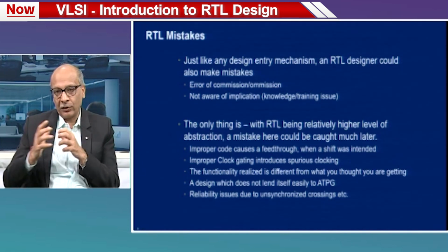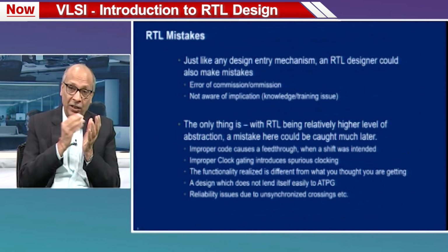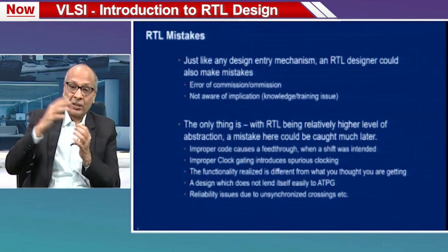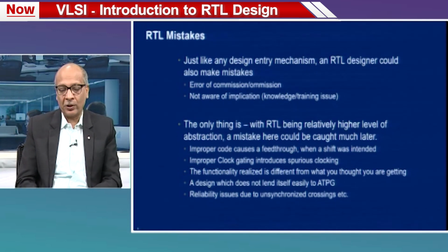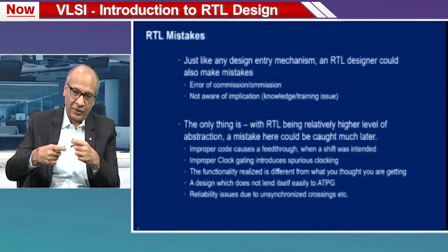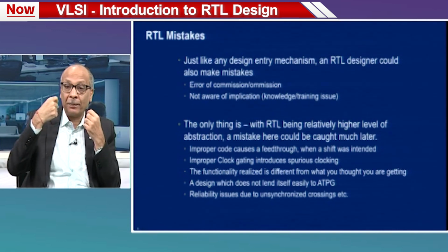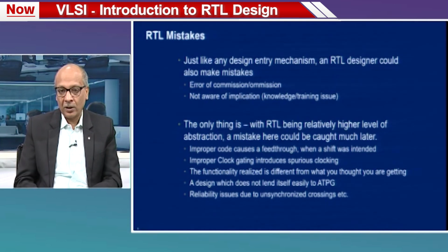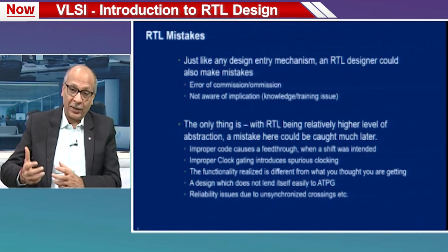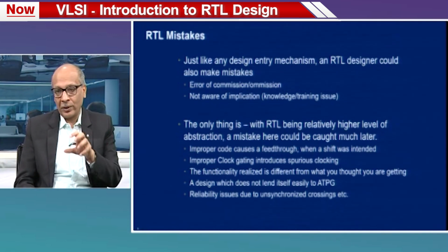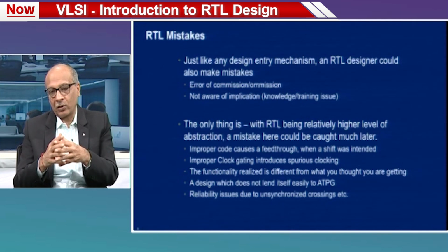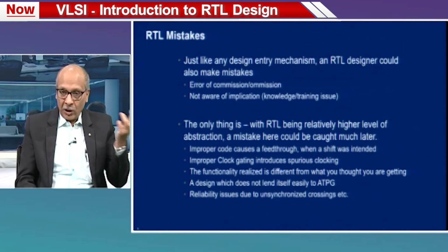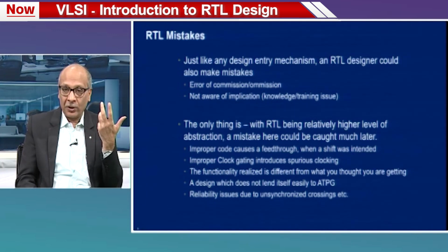So again, these are the kind of things that one has to take care of at the RTL stage, and if they don't take care of it at the RTL stage, then the effect could be felt much later. For example, the last one, the reliability issues: the effect will be felt when you run the device on the hardware multiple times. Sometimes you will see reliability issues showing up once in 600 times and so on. So that is after the device has been fabricated is when you get to know of it, right. So we want to make sure that all these mistakes are taken care of at the RTL stage itself. We talked about simulation, which will catch some of these, but not necessarily all of these.